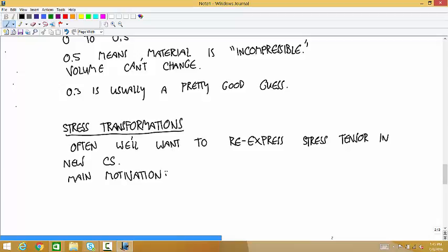And even better, when you find that orientation, you now have three normal stresses, or your only non-zero stresses. One of those is the greatest value of tension that's possible at that point for that loading, and one is the greatest amount of compression that's possible for that loading. And based on those two values, the third thing is you can find the coordinate system